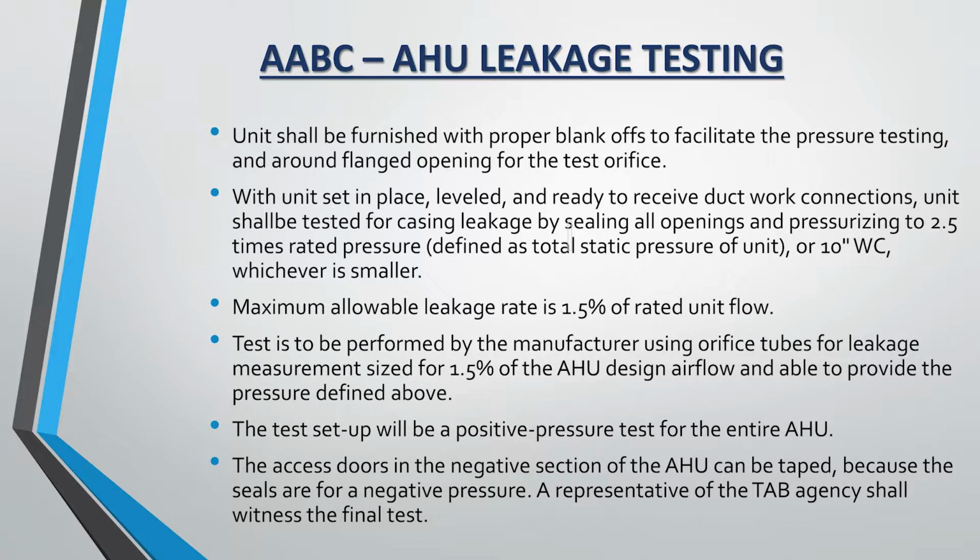because, as I alluded to a little bit ago, once the electrician gets to that unit and he starts drilling 3/4 inch holes everywhere to put his EMT, and then it goes to all his junction boxes on top of the unit or the side to run all of his control wiring, if they're not sealed off where the little wire goes through to whatever sensor or control device is in there, or the 2-inch hole to mount the VFD on the side of the unit, because that wasn't a provision from the manufacturer. He just drilled this hole, mounted the VFD, now it's on the side of the unit, and you're like, I thought that was getting mounted on the wall. No, we're putting it right here. Wow. So now we have this other hole.